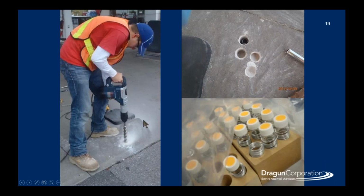So here's an example of drilling the hole that the cartridge goes into, and you can see that a single person can do that, no drill rig required. Typically they're installed just a couple feet into the subsurface, and they're left there for a couple of weeks. You cement over them temporarily so that they don't have any influence from anything that's going on above the surface. And a 2-person crew can put in as many as 50 of these in a day, depending on how difficult the drilling is with the handheld drill.